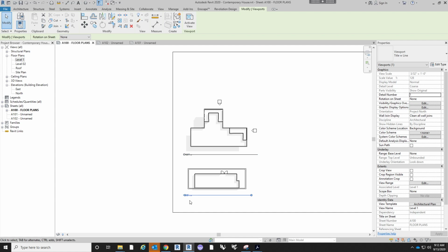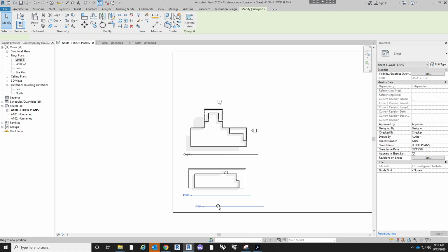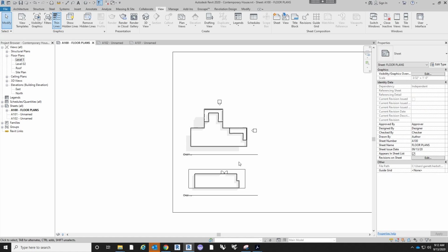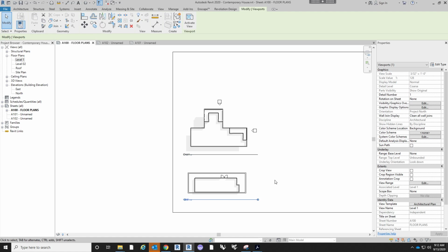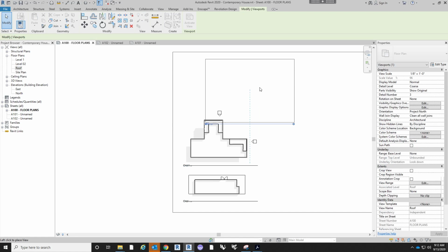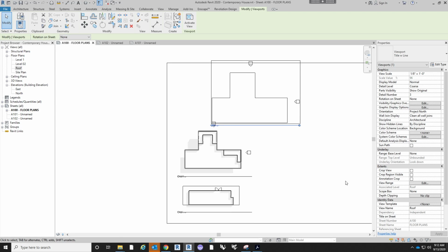The nice thing, to get these aligned, which with my OCD is very important, is you can click and drag, and once it's aligned on one side, the dash bar comes up. If you want to change the length, click on the drawing again, click that button, and once you have it aligned, those dashed lines will pop up again. Now that we have it smaller, we can probably add in the roof level. And real complicated stuff, that nice white outline. But we can add our roof template in.